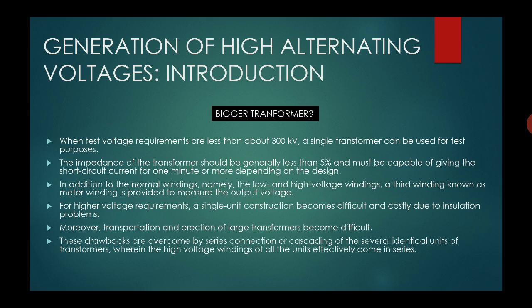For a higher voltage requirement, a single unit construction becomes difficult and costly due to insulation problems. Moreover, transportation and erection of a large transformer becomes difficult. These drawbacks are overcome by series connection or cascading of several identical units of transformers, wherein the high voltage windings of all units effectively come in series.